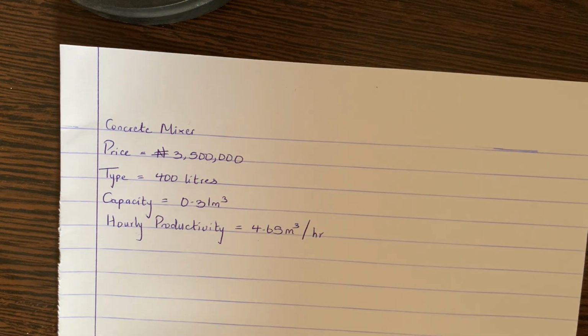If you are using a machinery, it means that when you are building your rates, you have to build your rates for the machine itself, the labor, that's the operator of the machine, and then the cost of fuel. Those are the three major things you are going to be using to build up the rates for your plant.